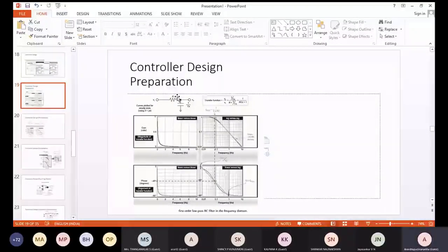The thing is, in any DC-DC converter which we are going to design, which we are going to handle in the afternoon session, buck converter and flyback, it is very obvious that it is a DC to DC converter. So there is no question of an AC component at the output. Okay, and also input, because it is a DC-DC converter. Anyway, we are interested only in the output side. At the output side, you cannot expect any AC. So AC has to be bypassed. That means we want to see only the low frequency component.